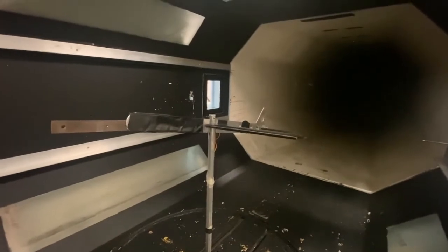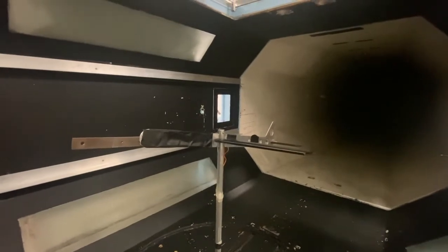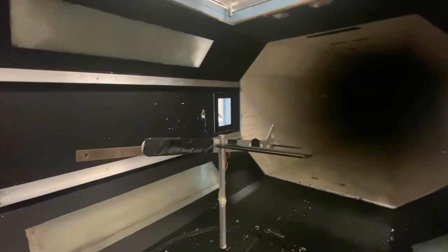In this experiment, we will be analysing the relation between change in angle of attack and the resulting pitching moment. The only control surface we have is the elevator at the back, which is constrained to the neutral position. As you can see, the fuselage and tail of this model is a flat plate. This was designed specifically for this analysis as we want to exclude the effects from these in the longitudinal and lateral directions. As mentioned before, there is only one actuator here, the elevator, and it is fixed in the neutral position with tape. You can also make note of the pushing rod here. To reiterate, the elevator is not deflecting in this experiment.